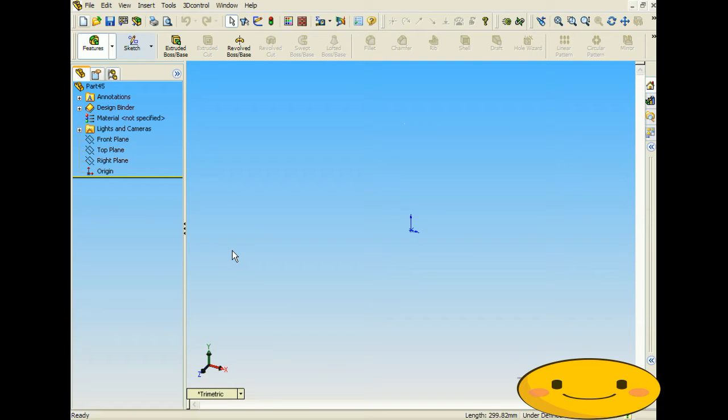So in this tutorial, we're going to be covering how to use the Spline on a surface sketch feature. What that does is it creates a 3D spline sketch on any surface that you have. So you don't have to create planes. You don't have to choose a plane to start sketching on and then use a 3D sketch to move it around or anything. All you have to do is click on the tool and click on any points on that surface.